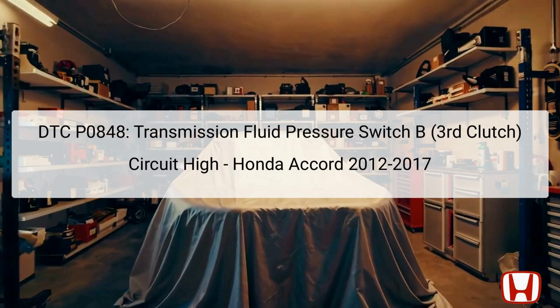DTC P0848 indicates a malfunction in the transmission fluid pressure switch B, specifically associated with the third clutch of the transmission system in the Honda Accord model years 2012 to 2017. This DTC is crucial as it pertains to the hydraulic pressure within the transmission, and it specifically monitors the hydraulic action required to engage the third gear of the transmission system.